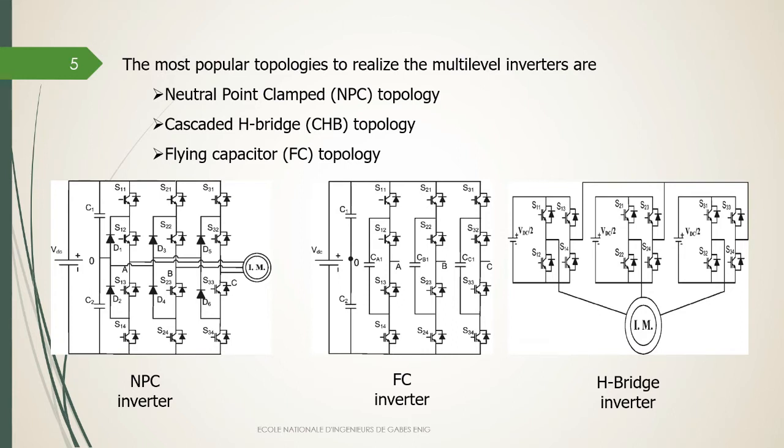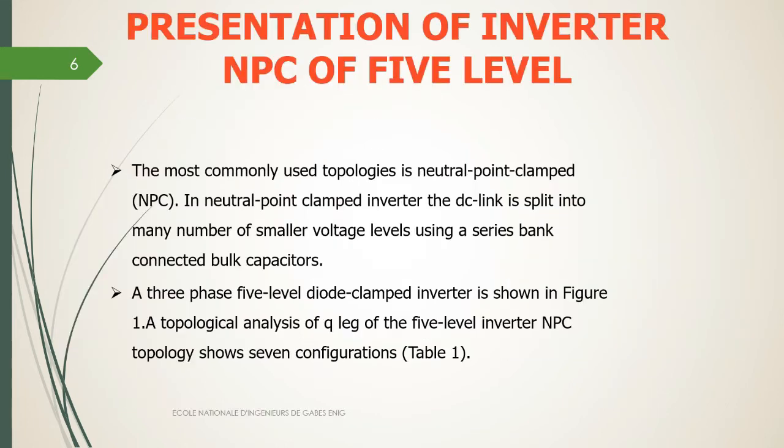We can see in the table the configurations and electrical quantities. To avoid short circuit of the voltage source by conduction of several switches, and so that the converter is completely controlled, a complementary control is adopted.